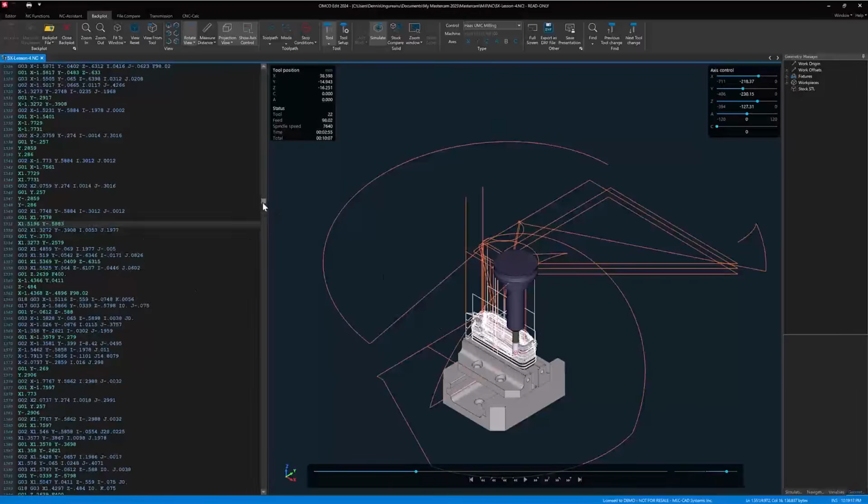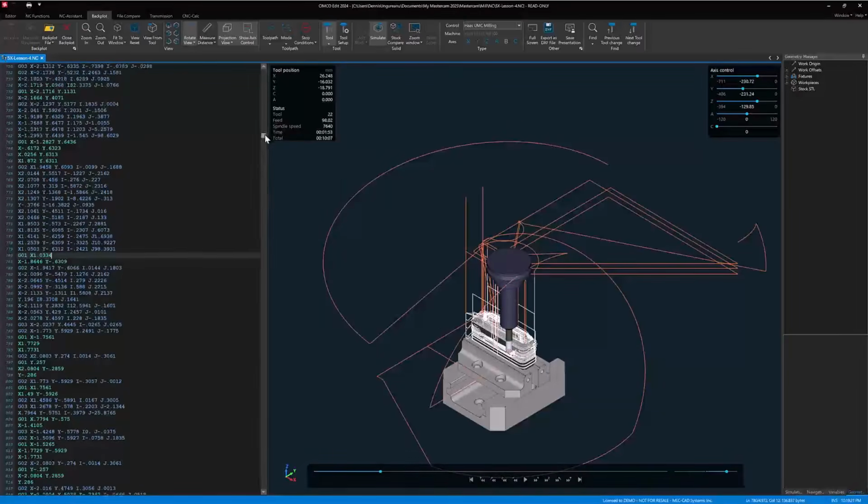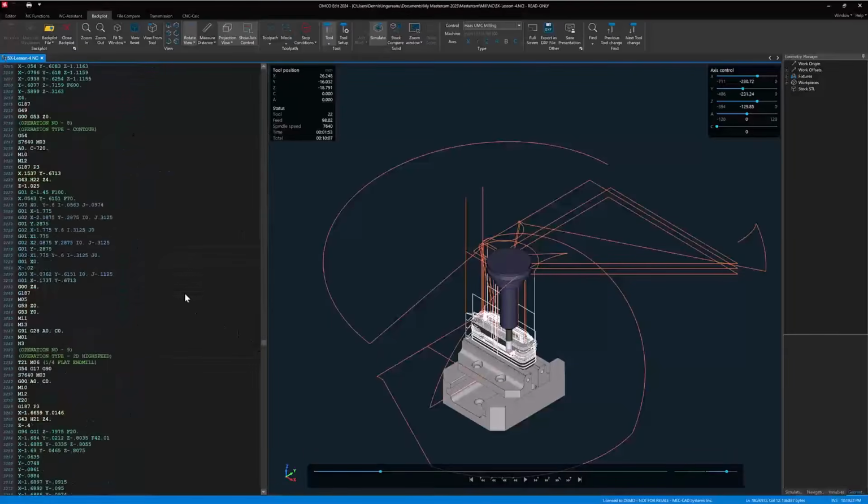It's in this section here. Okay. So we can always click here anywhere in the program in the NC code, and it'll launch the simulation or the backplot forward to that point. And we can obviously edit anywhere here. I can say, oh, the spindle needs to be backwards. We're going to go M04, and then save the NC code.